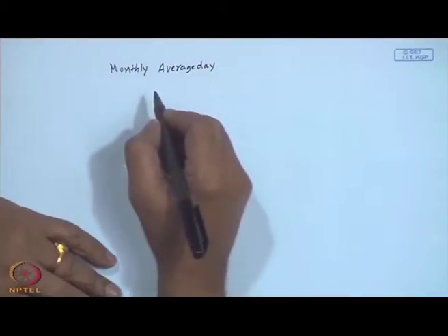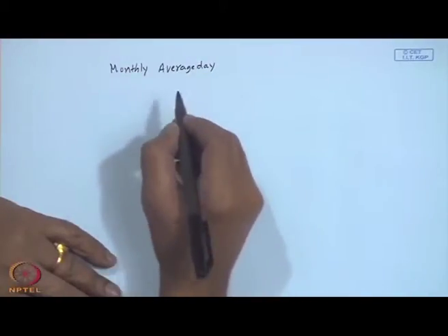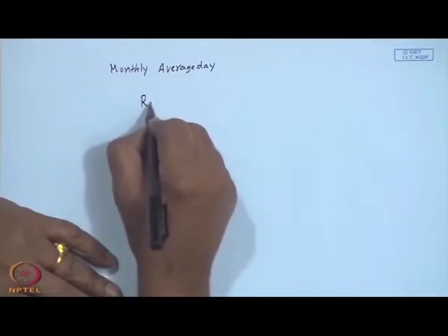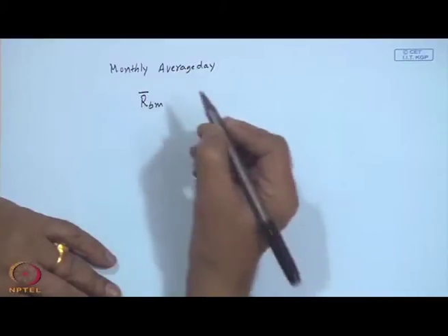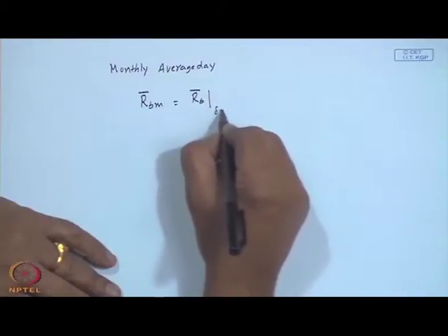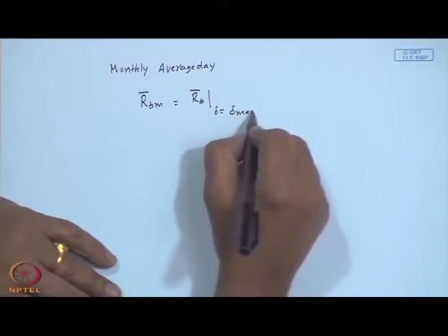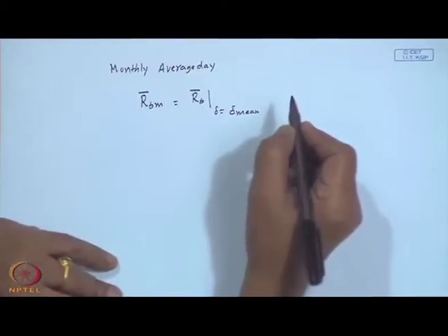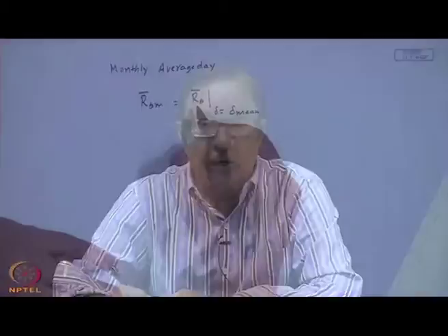as we have done for flat plate collectors or fixed slope surfaces, R b bar m for simplicity is nothing but R b bar evaluated with delta equal to delta mean, where delta mean is the recommended mean declination for each month. So, the formulas are known and there are analytical expressions for modes 1, 4 and 5, and modes 2 and 3 are not analytically integrable. So, one may have to go for a numerical integration, whether I b under terrestrial conditions is used or even